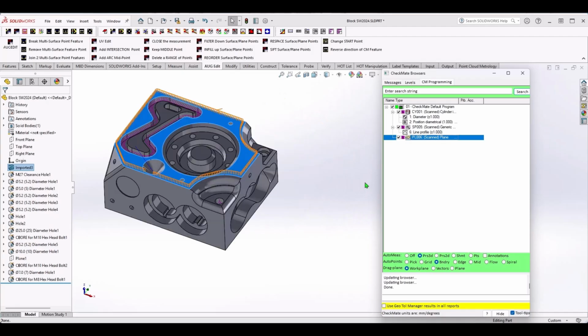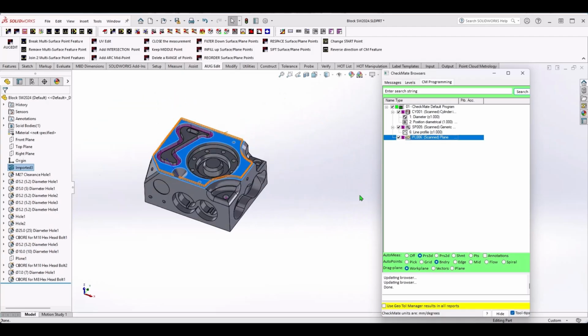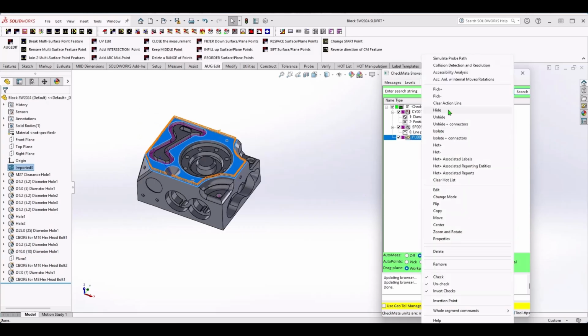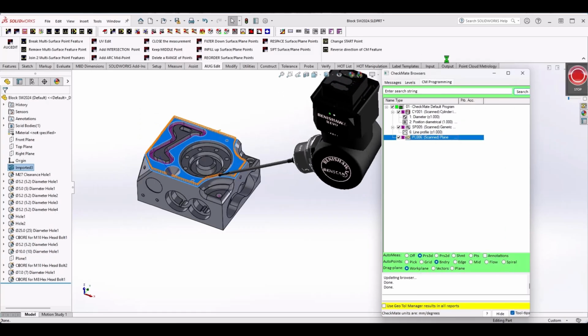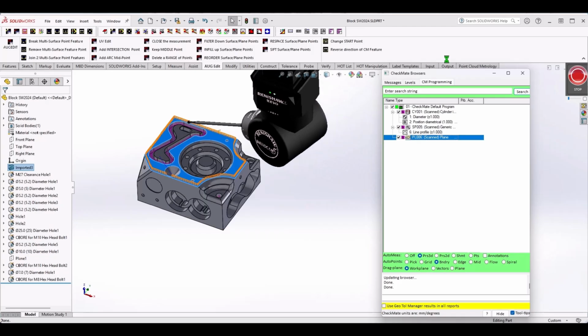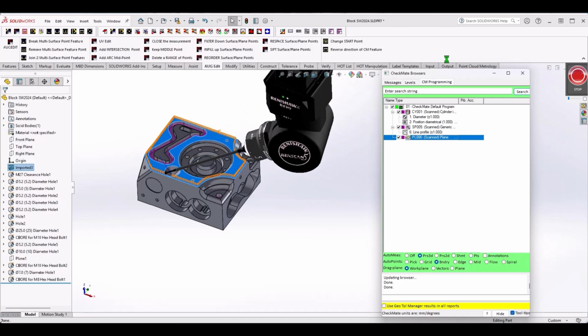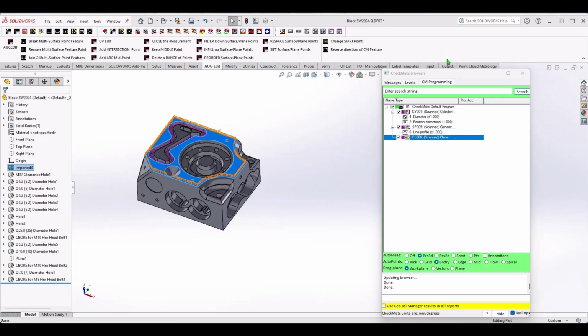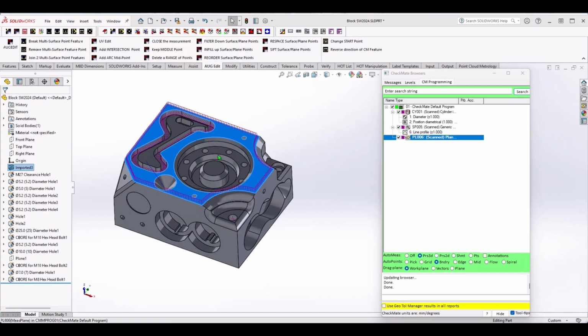So I'm just going to get it so that we can see more of the probe over on this side. So if you watch the carriage, it moves in one direction as that goes around, and the head does all the rest of the work. Eventually, that will wake up for the PH20, and it'll be doing little taps as it goes around. But the same idea, the carriage will only move in one direction.